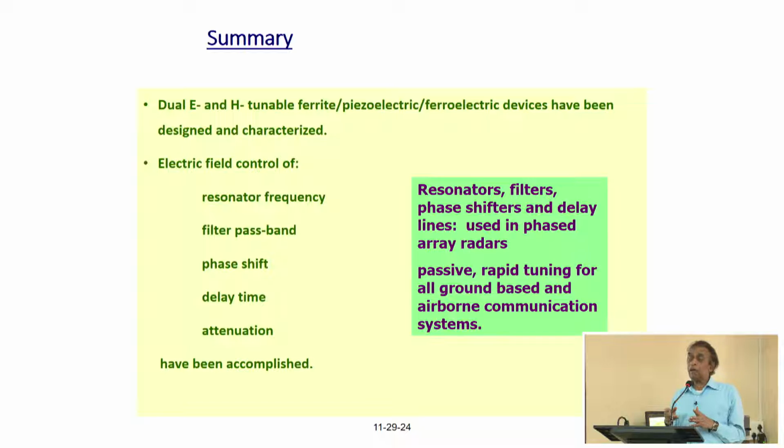But with a permanent magnet, the field that you apply to the film is non-uniform. That can lead to a spread in the FMR profile. So instead of 1 Oersted for the YIG line width, you may get 10 Oersted because of the non-uniform magnetic field. But if you can live with it, then you don't need any PZT or any voltage source. All you have to do is tune the magnet mechanically and you should be able to get it.